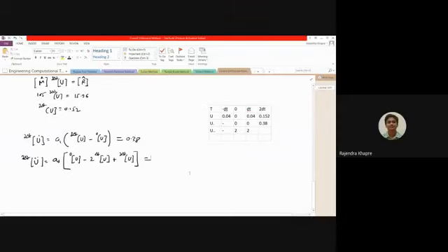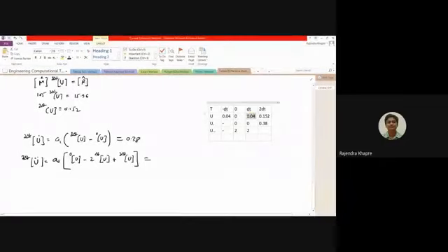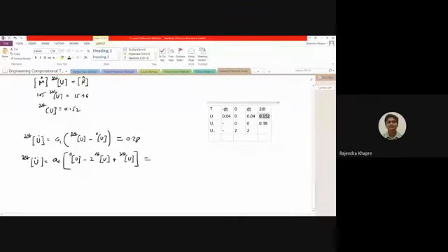The velocity at 0 is 0. The displacement at 0 is 0 over here, and then at delta t it is 0.04, and at 2 delta t it is 0.152. So how much is this acceleration? 1.8. 1.8. Very good. So this now becomes 1.8.